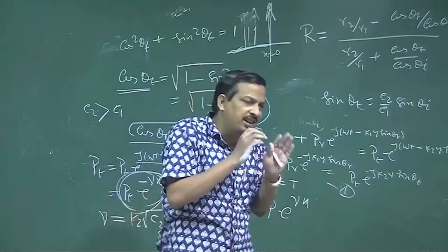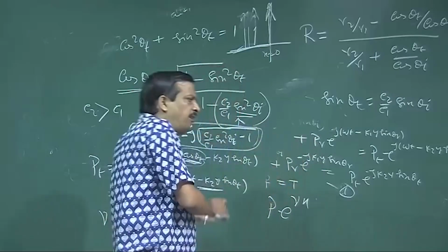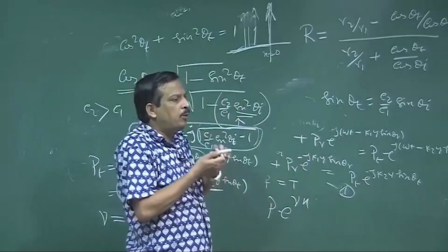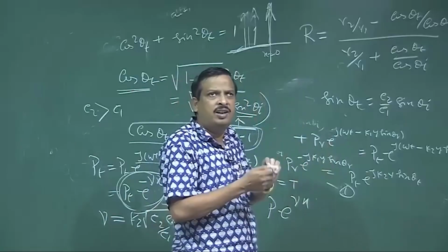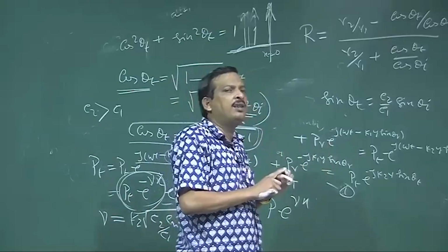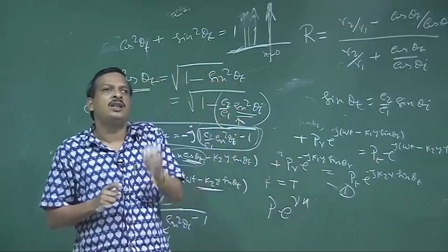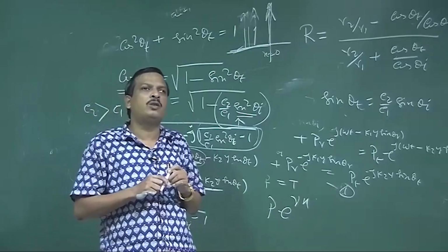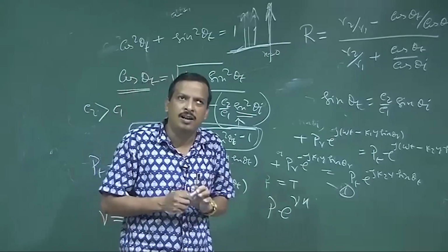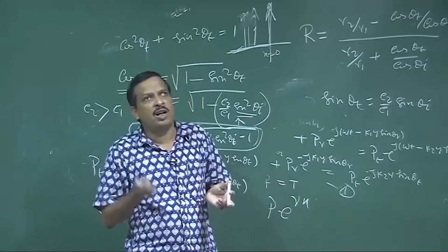Okay. So, that is the oblique incident case. For normal incidence, the wave propagates along the x direction only, and the y component is 0. For normal incidence we have derived that the pressure transmission coefficient is inversely proportional to L, and the intensity transmission coefficient is inversely proportional to L square.